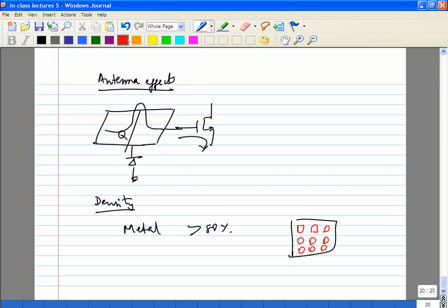So you will have to make sure. Typically for RF circuits, for the signal portion of the circuits, you definitely want to do what is called custom fill. There are auto programs. Obviously it will find out what metal layer is available already there, and it won't fill on that metal layer, but it will fill on other metal layers. Okay, but you don't want to do that.